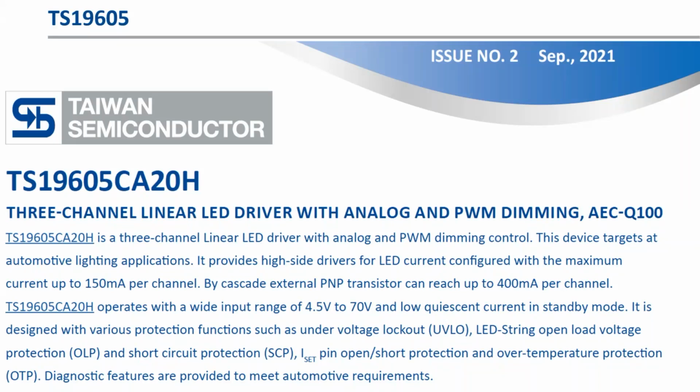It has a low quiescent current, which you would typically require for automotive applications. And it has a lot of features when it comes to protection. I'll talk a little more about them because everybody has their own way of doing it. You expect, of course, undervoltage lockout and some of the other ones, but it does monitor the LED string and can detect faulty, wrong LEDs.